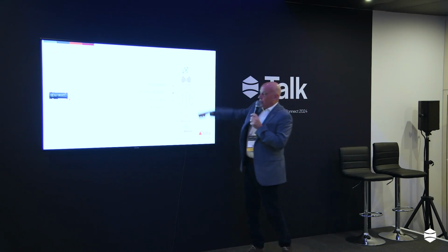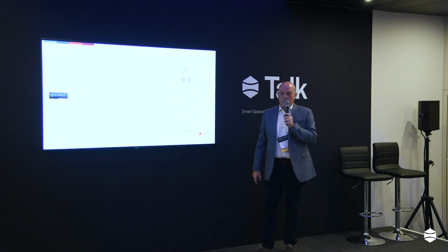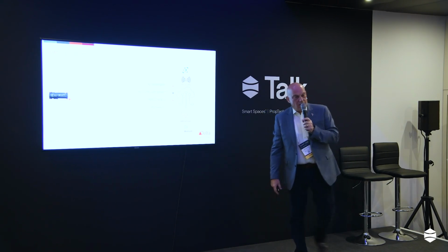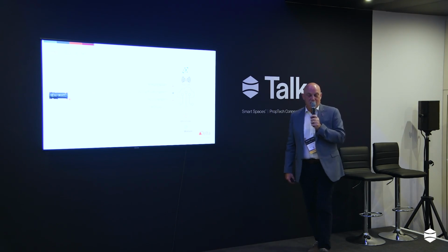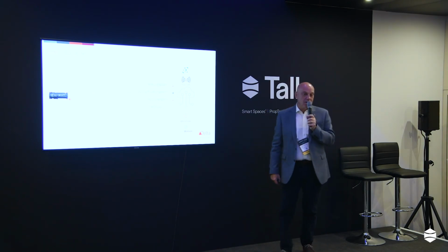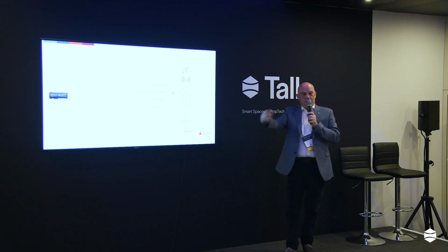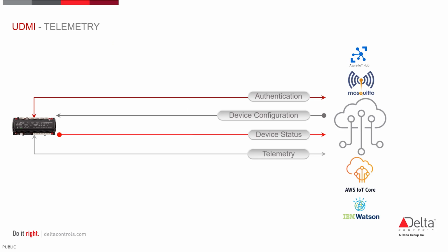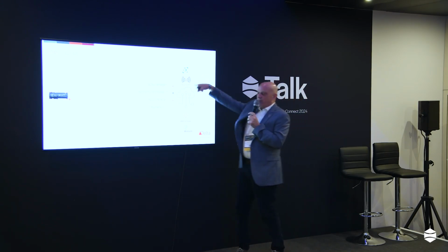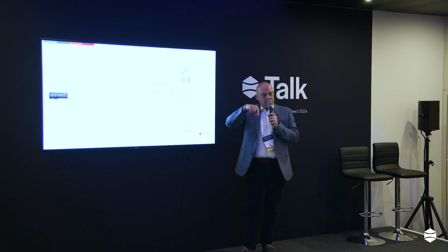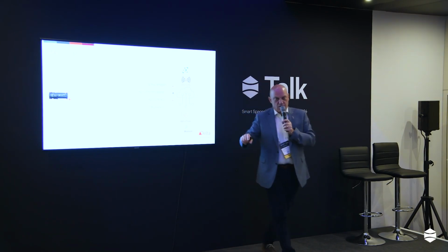It's also broker agnostic. It uses MQTT. MQTT, for those that don't know, I describe it as Twitter for computers. With Twitter, you tweet and follow. So I follow your feed. When you tweet something, I get a message. MQTT is exactly the same. I think it's the same platform, actually, but they call it publish and subscribe. I subscribe to your topic. When you publish to that topic, I get a notification. Same technology. And there are various MQTT brokers, IoT companies that provide this infrastructure. UDMI is agnostic. It doesn't care what the broker is. Each broker has different ways of connecting to it, but UDMI, in principle, once you've got the connection established, it doesn't matter because it's just MQTT.